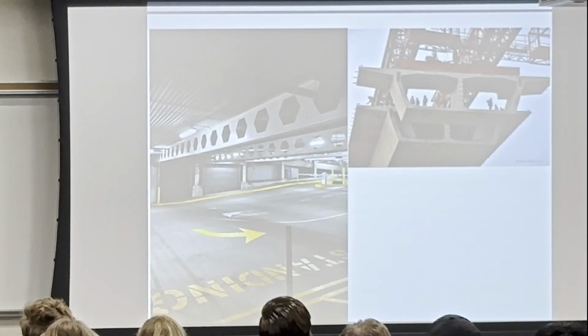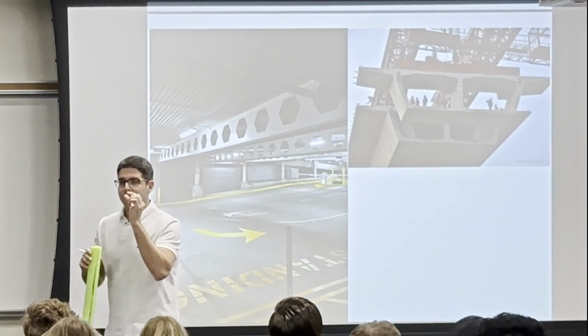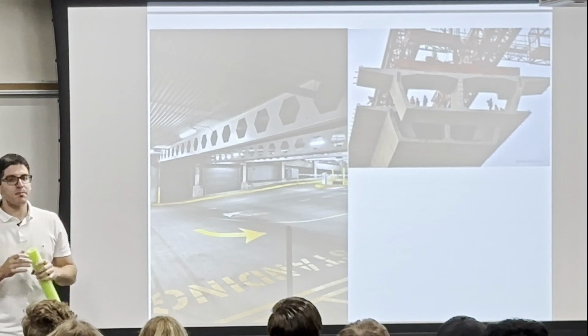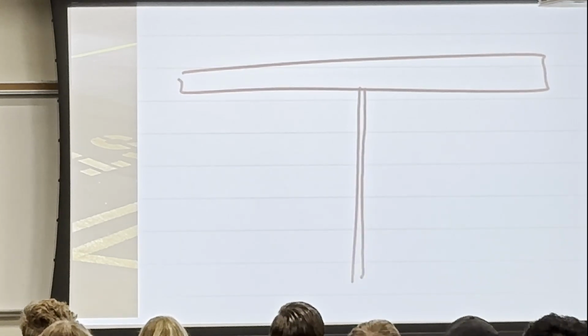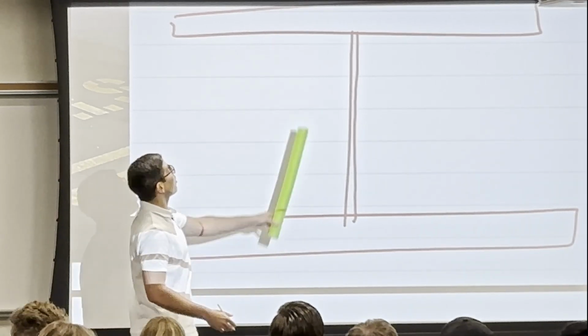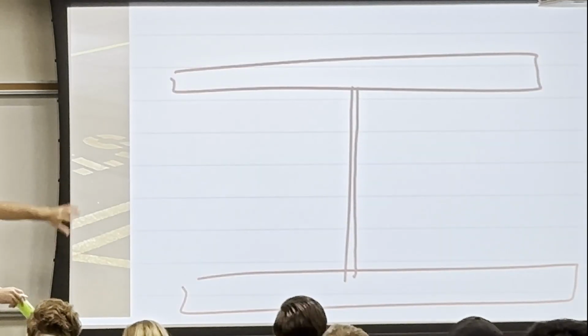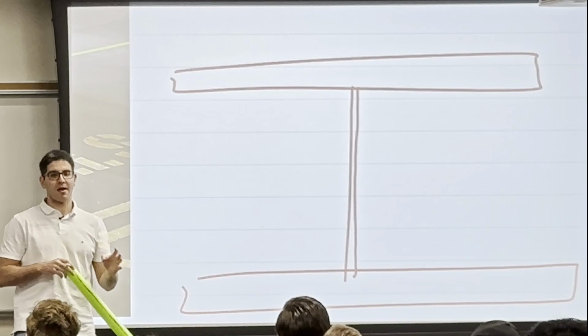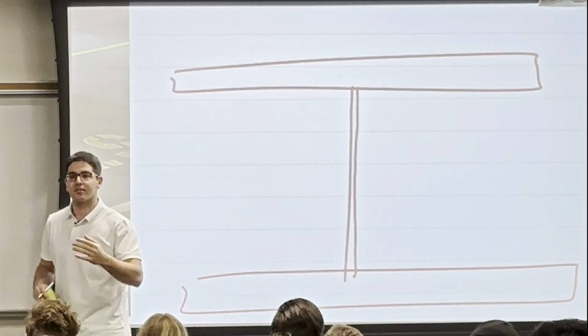But last thing before I close this lecture, I'm 1 minute, okay: I'm telling you to put the material away from the centroid. That doesn't mean that you will make me a cross section that is very thin like this and put it away. Theoretically, you will have a very strong bending if I give you material and told you just to allocate it. If you put a very infinitesimal section in the middle and put everything at the end, yeah, you will have a very strong bending stress. But this will fail right away in shear stress, which we're gonna discuss next week.